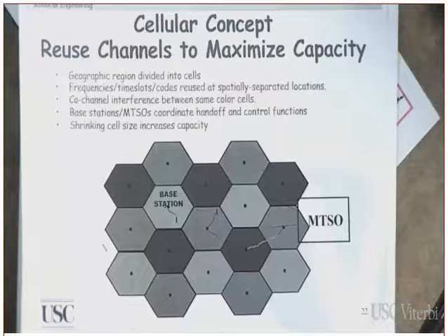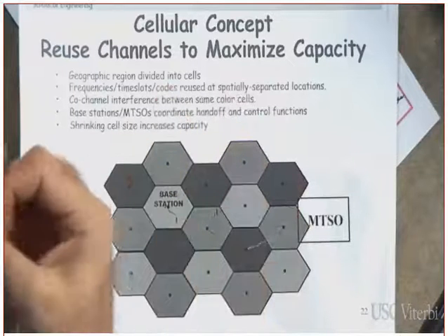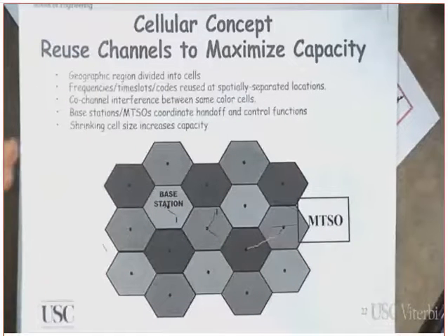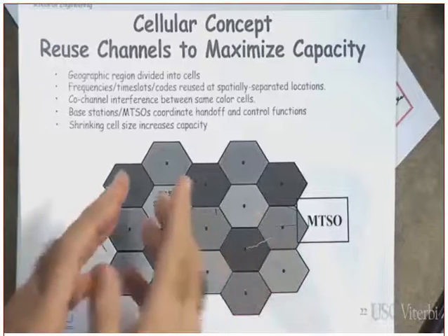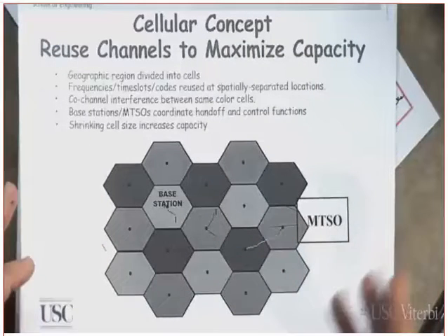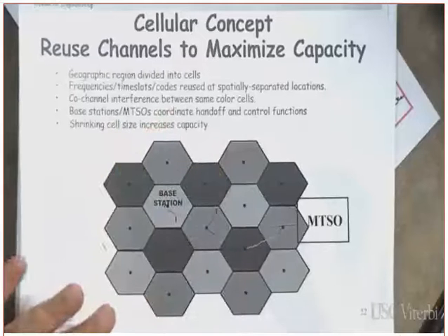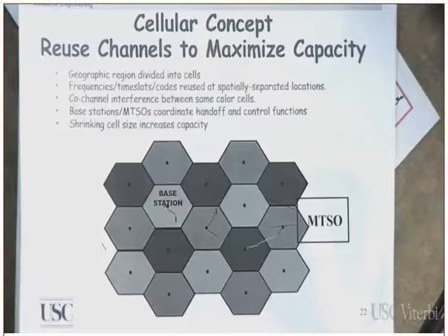The question here is that there is no empirical formula that I can just plug in. It's all based on measurement. Companies like Qualcomm take their truck and measure the received signal strength power, RSSI, in multiple locations within the area, and they come up with a mathematical model to cover how much the signal is losing. Clear? So if they are separated, the longer the distance is, it means the signal will lose its strength, which means the interference will become lower. Clear?